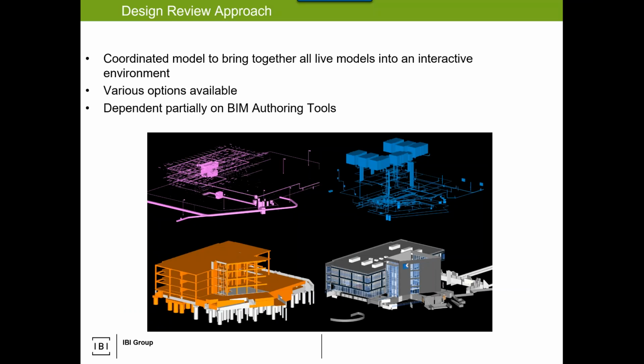So from the design review perspective, the concept here is, you know, not the burden, but the task placed on the BIM coordinator is to help facilitate bringing all of this stuff together. And, you know, it is much easier if you're in the world of a single application and you're working together. So this here example, this is 4 Revit models. They could be linked together and you could model around each other. Now there's burdens and drawbacks to having multiple links in your live models.